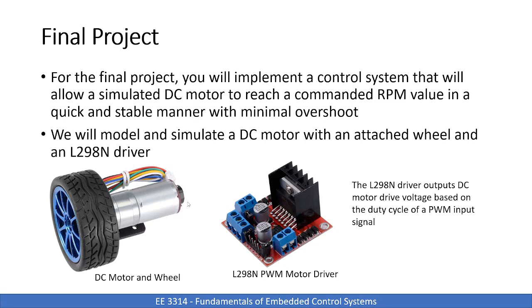That is a rotary encoder that is sending A and B channel pulses out, so we can use the microcontroller to interpret those signals using encoder mode, and we can measure the RPM, so that provides the feedback. When we're simulating this, that'll be a more mathematical thing, but you can actually do this in hardware where you design only the control system in the microcontroller, and the measurement of the rotation is done physically with this encoder.